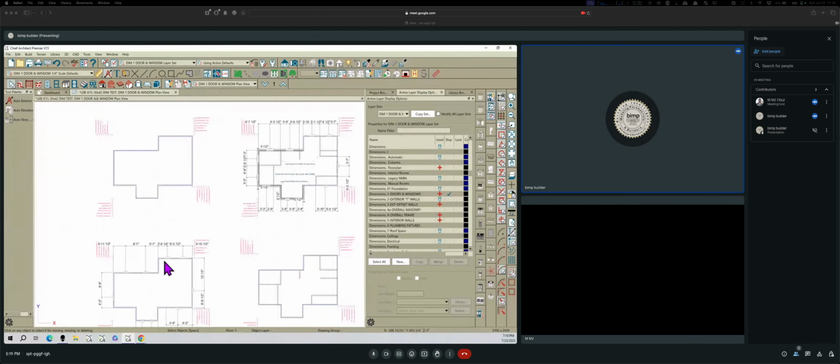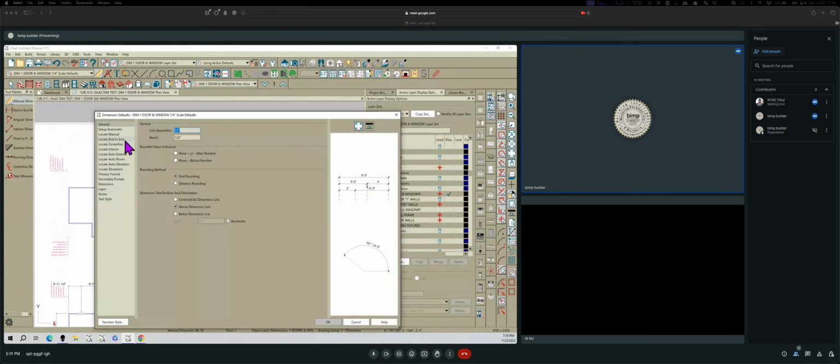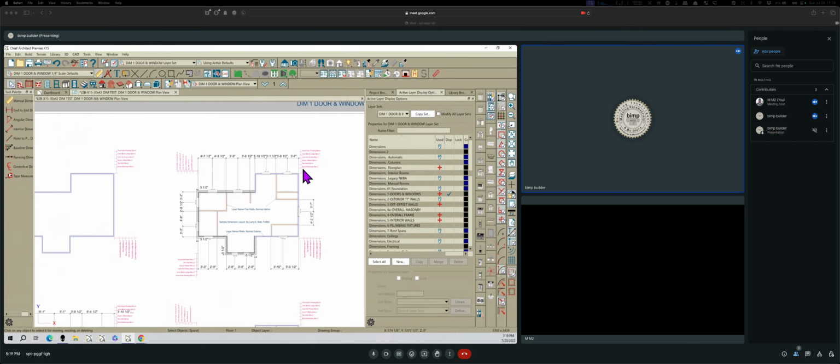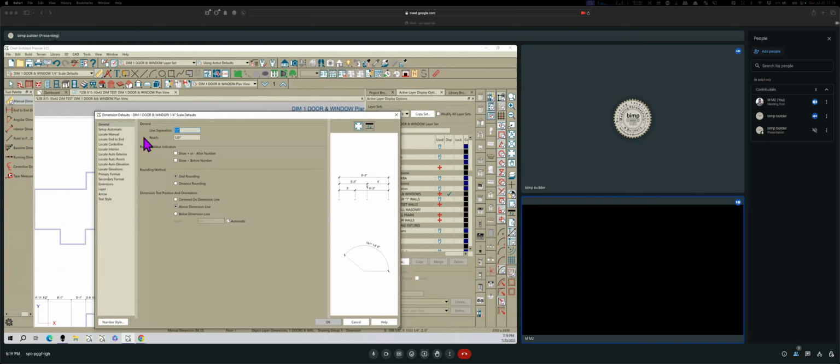See down here, it's putting the windows in, but I don't have it set right because it's got to be down. So I've got to go and set that where it's the right height. Well, it says it's 20. It's supposed to be 20 inches off, so I don't know why it's not doing it. And how come some of them have line separation of 14 and some have 12? I wonder if that makes a difference. Well, they're supposed to be all 12. That's what I have. I was looking at the next page, where it says set up automatic.